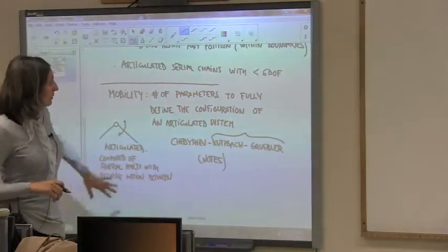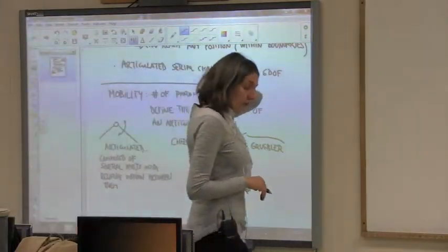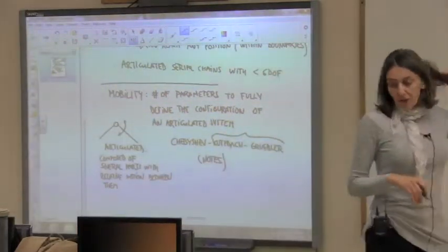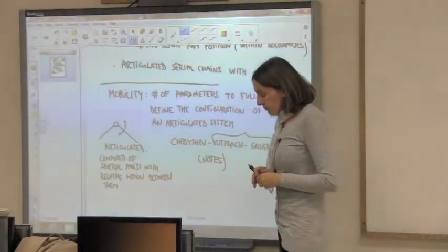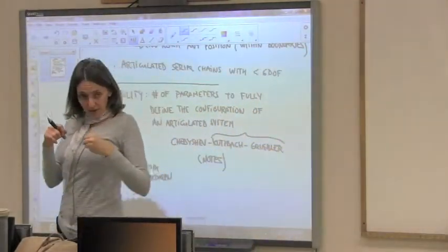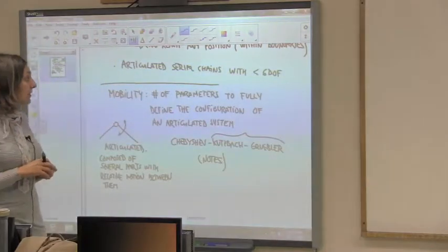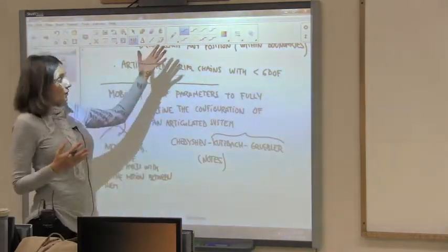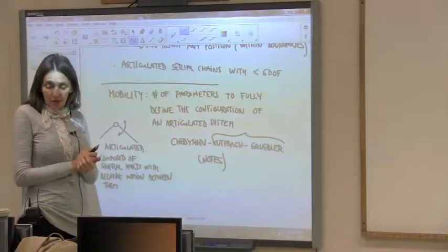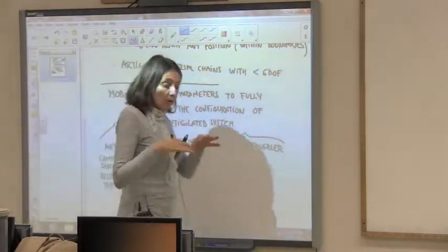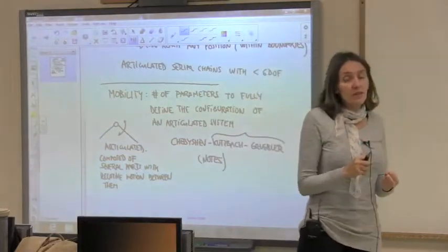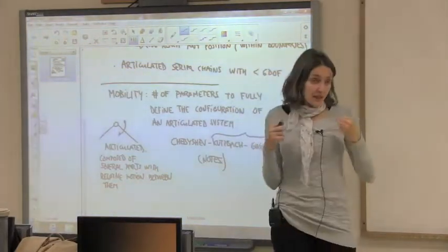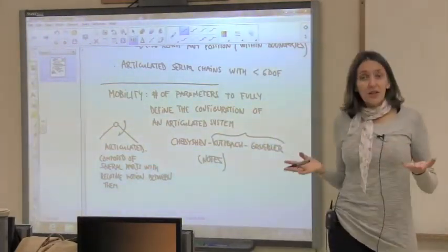Anyway, this is all related to the problem of the synthesis, in which we try to synthesize systems that move, right, for a given task. And those are especially important and meaningful when you have less than 6 degrees of freedom in your system. So the whole motion or the whole configuration of your system gets defined with less than 6 joint variables. And that's not so uncommon.